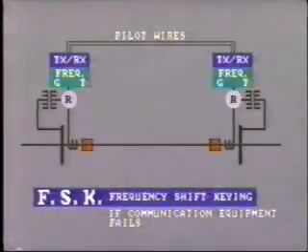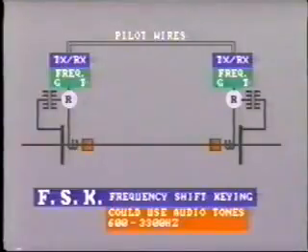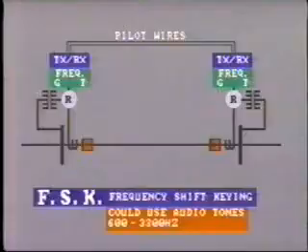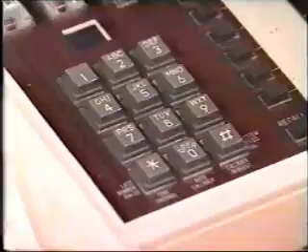It has the advantage that if the communication equipment fails at any time, loss of the continuous guard signal will be noticed and appropriate action taken. Another application of the FSK system uses audio tones. This method works by changing frequency, but the actual range of frequency used is much lower, about 600 to 3300 hertz. This is within the sound range of the human ear, hence the term audio tone. We are all used to hearing these audio tones when using the telephone.